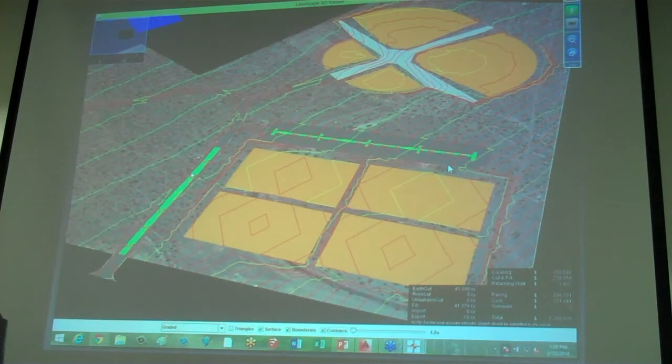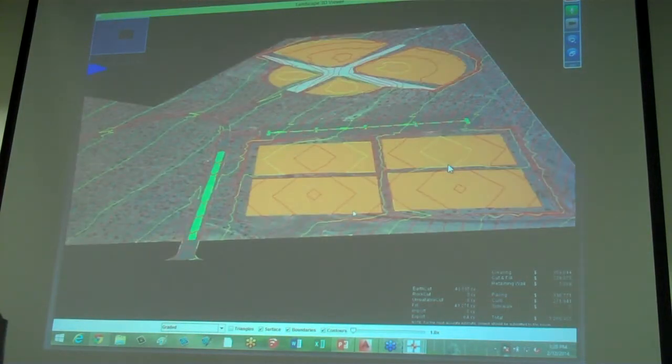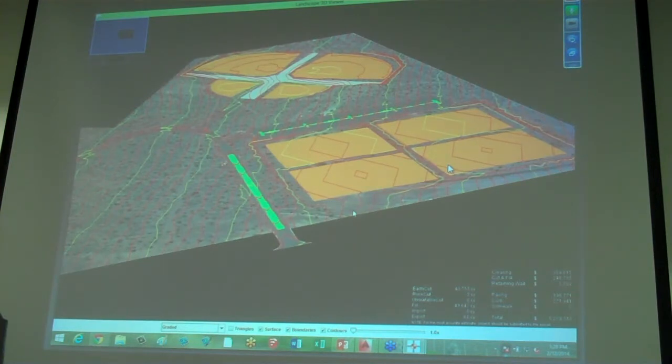Again, I can control K values for vertical curves and things like that. The parking is grading, taking into account that base. It's in the middle of the soccer field. And I'm not doing a 2D design, I'm doing a 3D design. But the best part is I don't have to click a button to see how this site plan is starting to look.